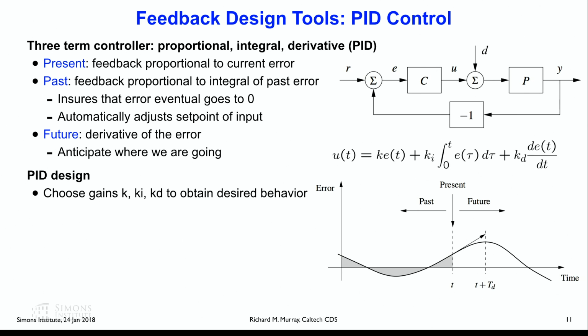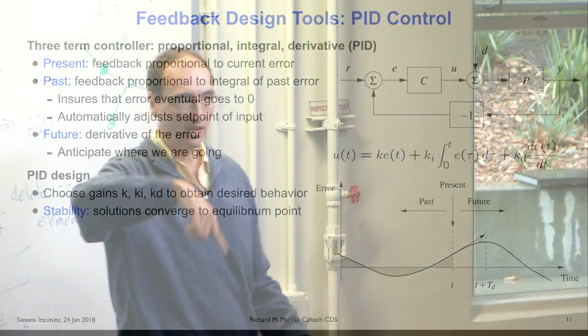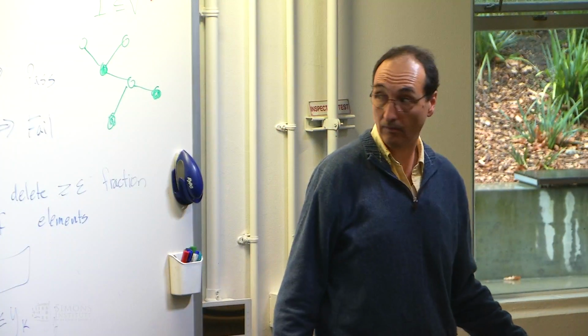What do we want it to do? To this question that came up earlier, what's the specification? Well, first, we want it to be stable. That is, when we put this feedback controller in there, we converge to a fixed speed and don't oscillate. Because we could oscillate with this stuff. I could integrate the error and apply a bunch of input, then start to slow down, and then I integrate the other way. You can get oscillations quite quickly out of this if you're not careful.